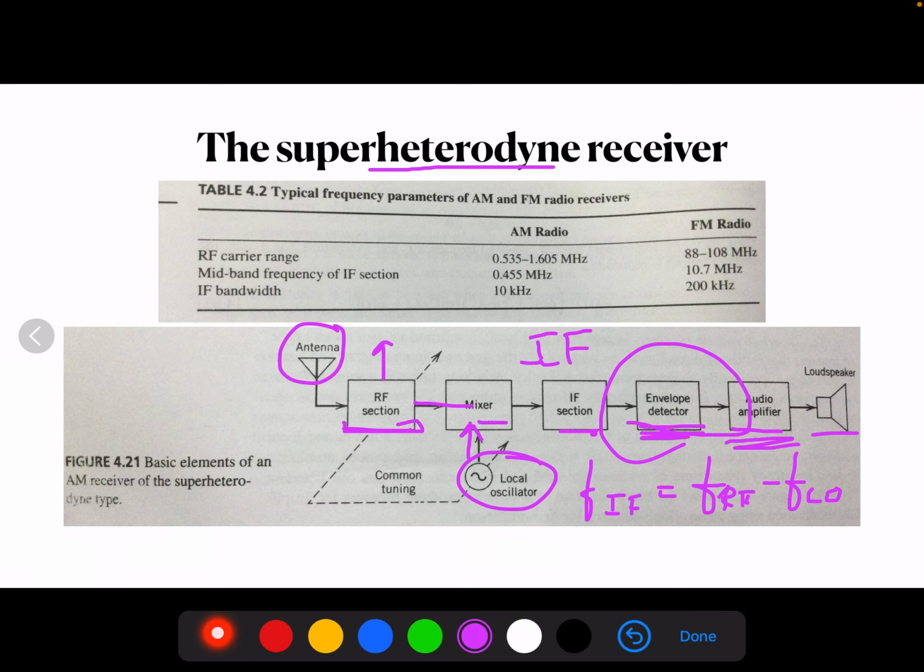The difference between the AM heterodyne receiver and the FM heterodyne receiver is the FM demodulator we use, or you can say a frequency discriminator. In FM, this is an AM receiver. Suppose you are using an FM system: the message information is transmitted by variations in only the frequency of the carrier signal, and the amplitude is maintained constant. The rest of the concept is the same. So any variation in the amplitude of the carrier at the receiver is due to noise or interference.